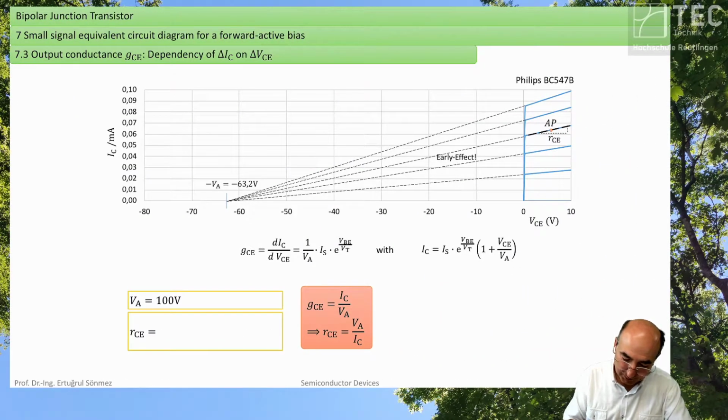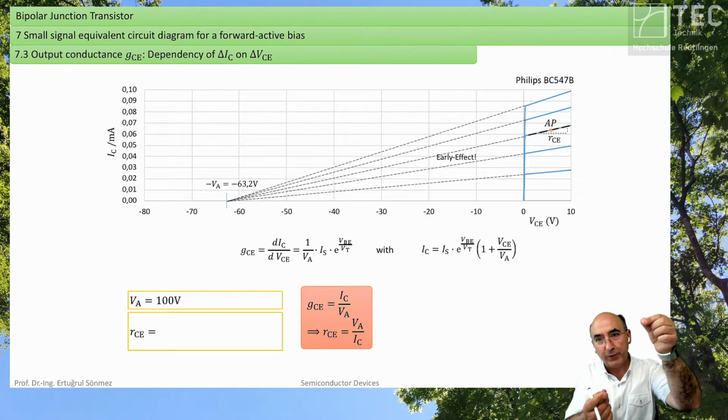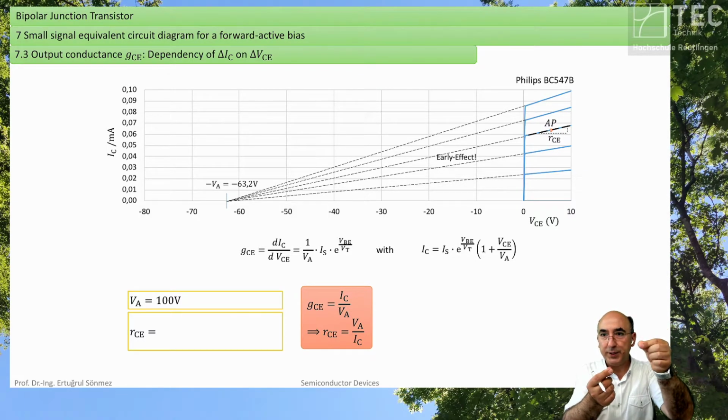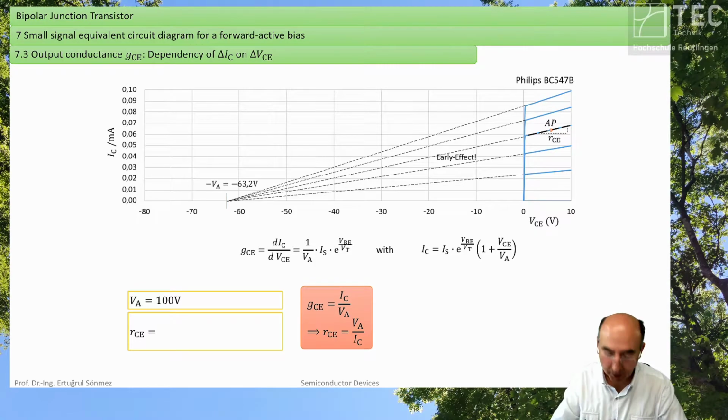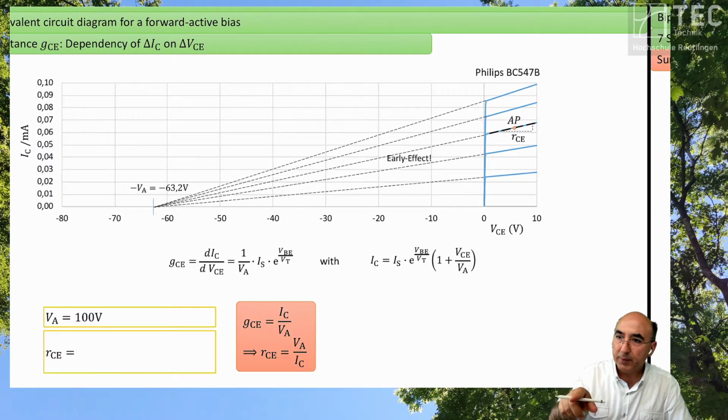And so this slope, the physical cause was the neutral base width modulation. The neutral base width modulation does make a slope variation of the diffusion charge triangle, and the slope variation makes the current variation. Okay, so after this slide, Mrs. Akbal, you can just drop your question you wanted to drop so all can participate in the answer.